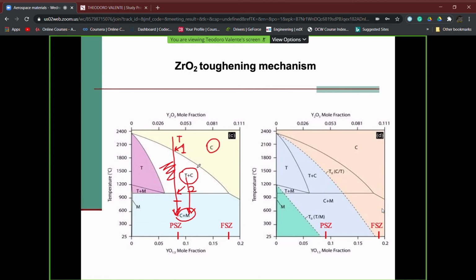And where is the trick here? The trick is related to this tetragonal zirconia, which is going to exist at higher temperature value, which is going to be transformed to the monoclinic phase only if we leave to the material, for example, on cooling, all the time which is necessary to the transformation to happen. But we know because we have experienced this also in metallic alloys.